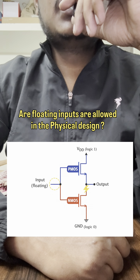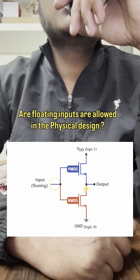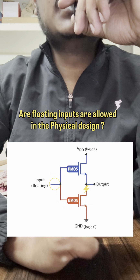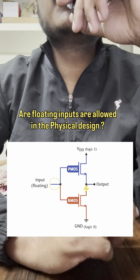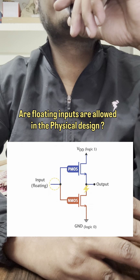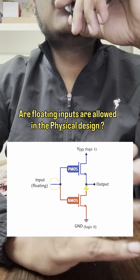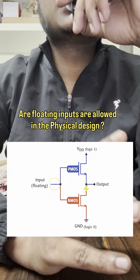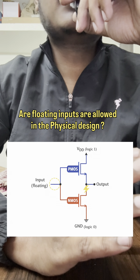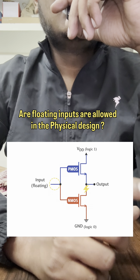Since the MOS gate is insulated by oxide, it behaves like a small capacitor with very high impedance. Because of this, the voltage at the floating input can drift due to capacitive coupling or leakage current. Suppose this floating voltage settles somewhere in between the threshold voltages of the transistors. In that case, both PMOS and NMOS can partially become on at the same time.